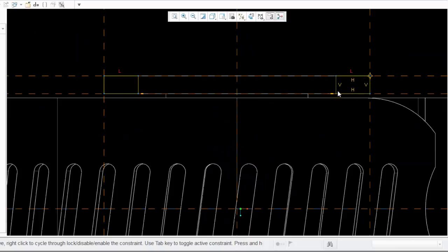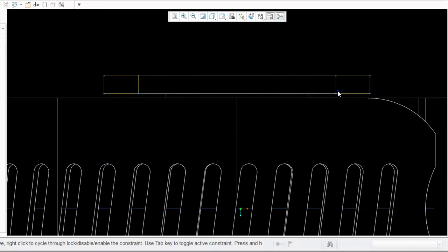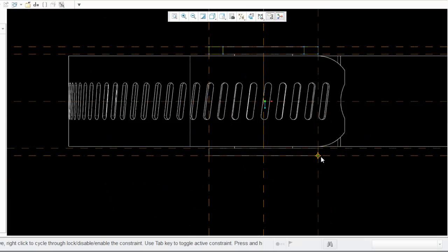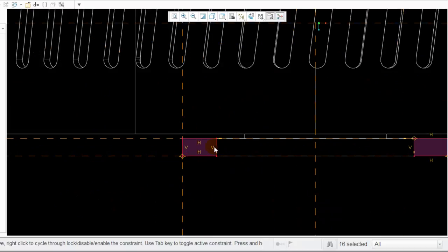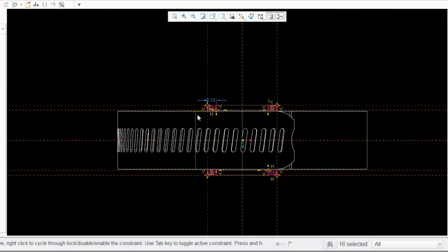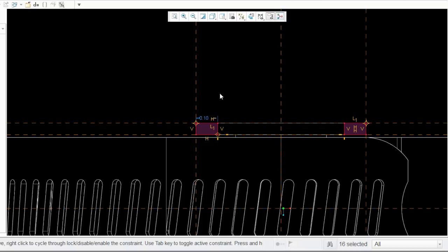Okay, I'm gonna lock that length on. So right click, got that length equal. Do the same for this one. Actually, I'm gonna lock that alignment up. That's fine. This one. There. It's all aligned. They have a line, a line. So everything's lined up. Only one dimension should be driving all four, and that's what I've got.